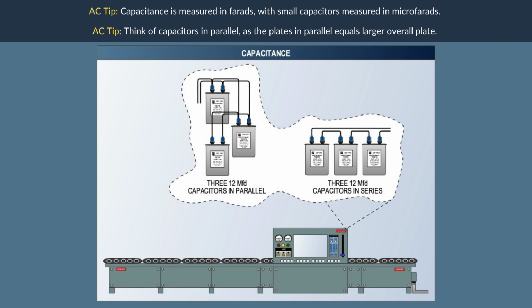When one plate of the capacitor has an accumulation of electrons, the electrons on the other plate will be pushed away, so one plate will be negatively charged and the other plate will be positively charged. As an alternating current charge is applied to the capacitor or condenser, the negative charge on one plate will cause a proportional positive charge on the opposite plate. As the charge on the first plate changes to positive through the sine wave, the opposite plate will change proportionally